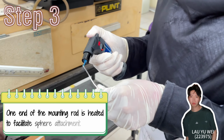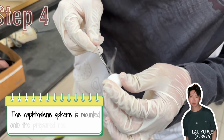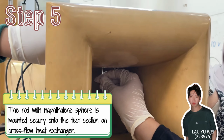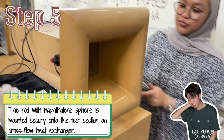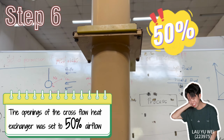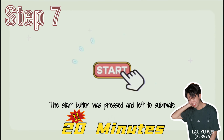Before that, one end of the mounting rod is heated to facilitate the sphere attachment. The naphthalene was then mounted on the rod. The rod with the naphthalene sphere was then mounted securely onto the deck section of the cross-flow heat exchanger. And the opening of it was set to 50% airflow. Then the start button was pressed and left to sublimate for 20 minutes.